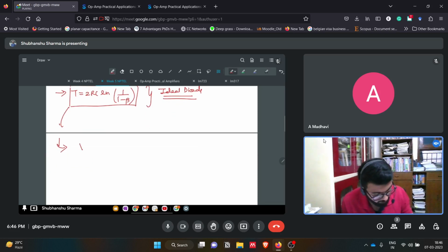Again we'll use the formula Vc of t equals V final plus V initial minus V final, times e to the power minus t by RC.